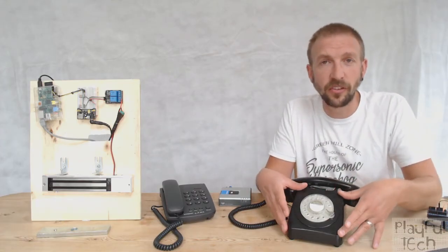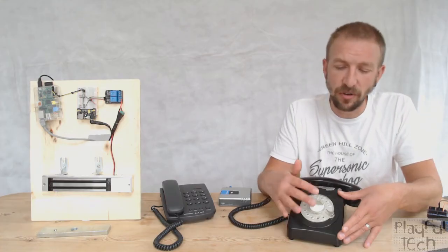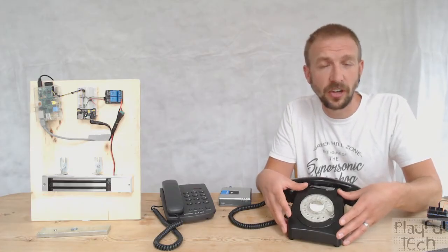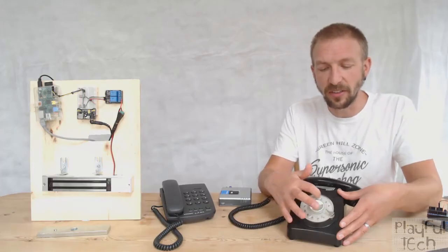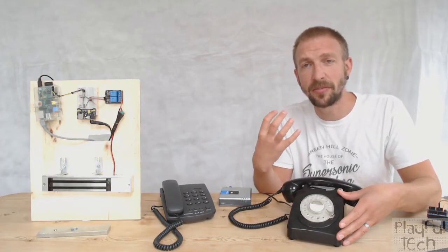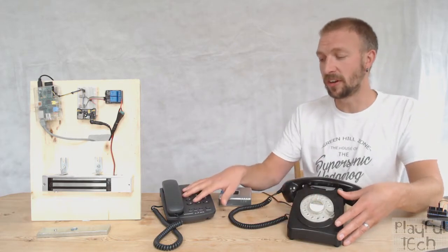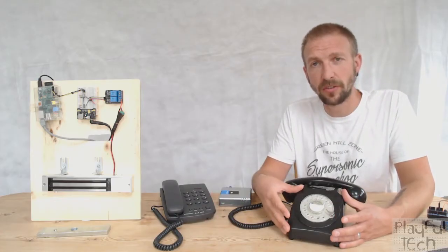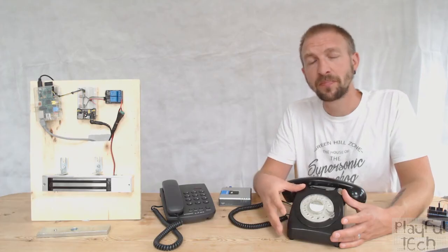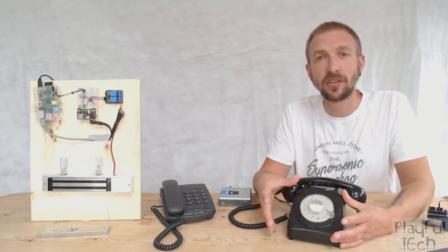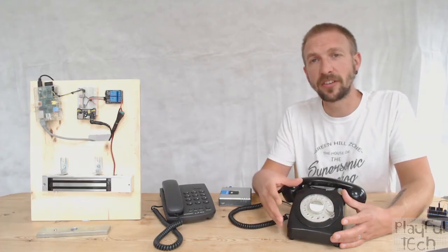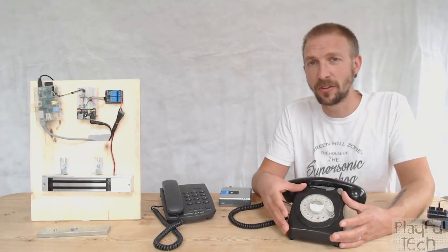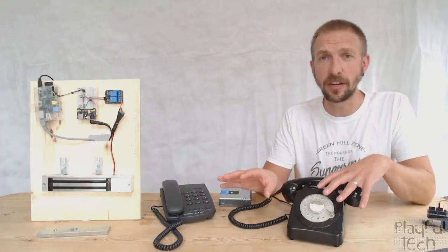This one is obviously designed to look like an old-fashioned rotary dial handset, but it's actually a modern handset that uses tone dialing. So each of the keys here will create a DTMF dialing tone on the line. This one's obviously a more modern style, and it's important that you do have a phone that is designed to work like that. If you've got one of the genuine old-fashioned phones that uses a series of pulses, what you'll need to do is to first get a converter for that to generate tones instead. It's possible to get them online. You could probably make one yourself if you're handy with an Arduino or something like that as well. But it does need to generate tones to work with the system.